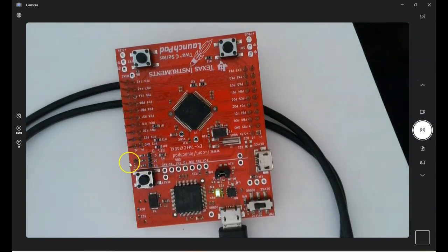But if you notice the rate of blinking, or rate of flashing, it's a little bit faster than the 1 second that I plan to have. Remember the calculation that we did? We said we want a 1 second interval, but this is faster than 1 second interval. So let's check the outputs with a logic analyzer.